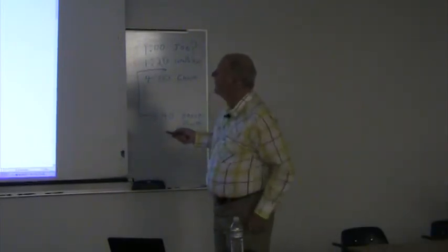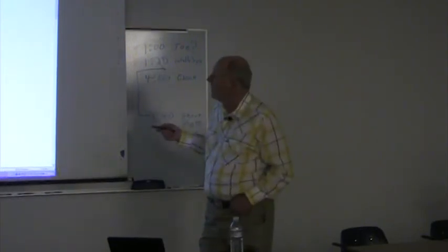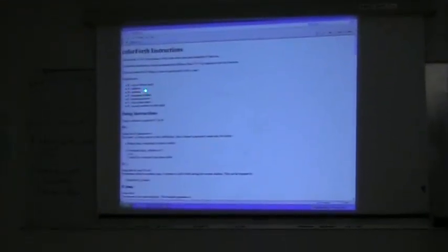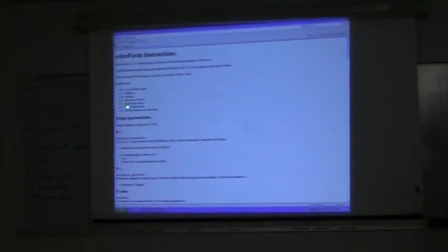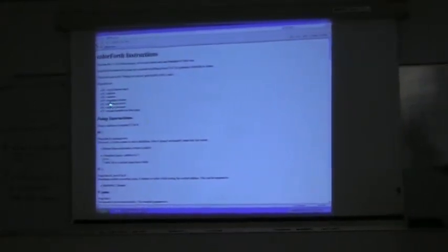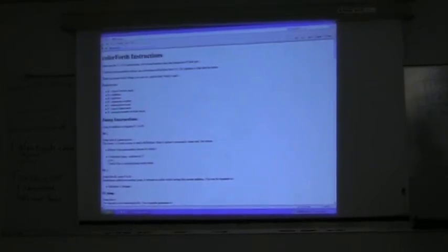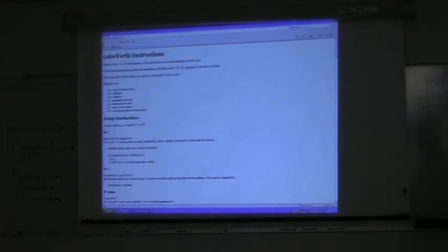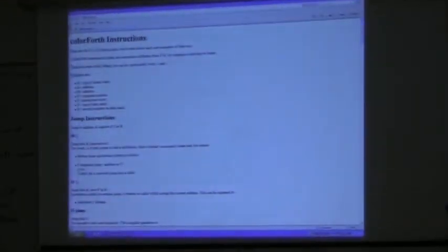There we go. These are the registers we're going to be talking about. R is the top of the return stack. A is the address register. B is another address register. P is the program counter. I is the instruction word with 4 instructions in it. T is the top of the data stack, and S is the next element on the data stack. That's really all you need to know. That's the architecture. Some of these registers talk to each other, some don't.